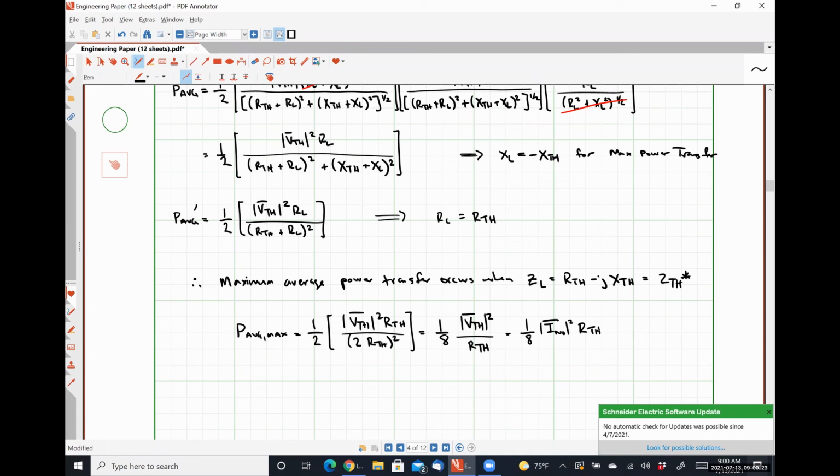Now, that sinusoidal signal that's being superimposed occurs only in underdamped systems, and it's behaving sinusoidally because the natural frequencies of the system are complex conjugates. Euler's identity effectively tells us that when we have those complex conjugate natural frequencies, they're going to interfere in such a way as to look sinusoidal. Yeah, so math is a fantastic reason.